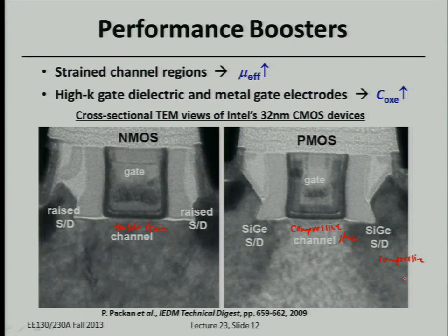The question is how much strain? That's a good question. The silicon has a strain limit. It'll crack, if there are any material scientists in here, if you really put too much strain on it, like more than 2% strain. So the amount of strain in here, I don't know, let's see, Peng, do you remember? It's approaching 1% in the most advanced technologies today, right? But if you go much beyond that, you'll see cracks. Actually, defects start to form in the silicon. Yes, Haley?